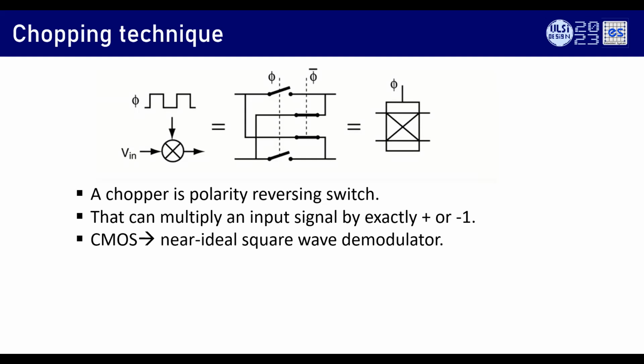Chopping is a known phenomenon, just a brush up. In chopping, you take the signal, go to high frequency, process it, and bring it back to DC. In the process, only the offset and flicker noise go to the high frequency, they don't come back to DC, so you filter them off. So you remove the offset that way.